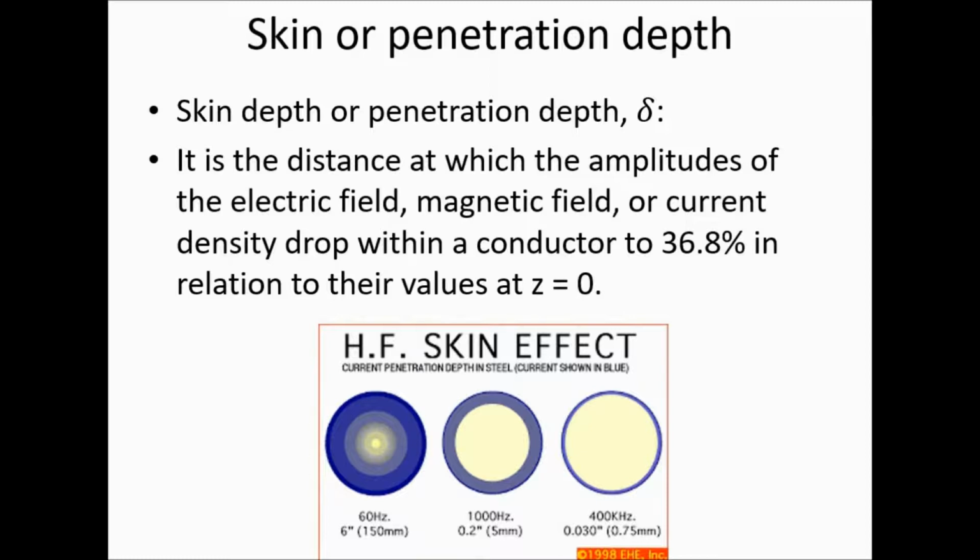If we design a thick wire, the resistance of the wire will be low, and the power loss inside the wire will be low. But after some extent, the increase in radius will not be useful, as electric and magnetic field and current are distributed around the surface of the conductor because of the skin effect.